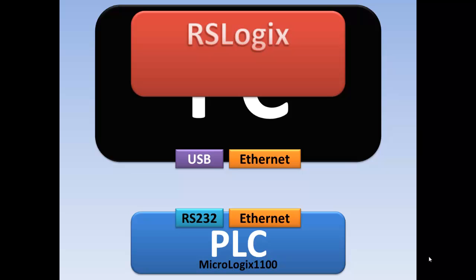But be advised, you can find both the USB adapter and the cable available on eBay and other locations for under $30. I find them a combination for $15 to $20. Don't hesitate to buy things on eBay, but you have to pay closer attention to what you're doing. So if you actually type in PM02 cable, when you search on eBay, you will find not only the original Allen Bradley cables for sale, new and used, but you will find substitute cables that are quite a bit less expensive. To that USB port, let's tack on an RS-232 adapter. So now we have 2 ports on the PC and 2 ports on the PLC.